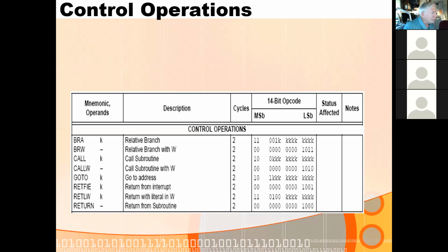And that's maybe the one time where you might actually have to use the PC latch high and then write the program counter low to actually do the branch. But an easier way to do it would be to branch to an intermediate point and then branch from there, and you can set those up within your code if you really had to. But normally you wouldn't have to do that. But if you wrote a really big program, you have to keep that in mind. But here's the nice thing: C is smart. It takes care of that for you. But if you wrote a really huge assembly language routine, then you might have to deal with that.